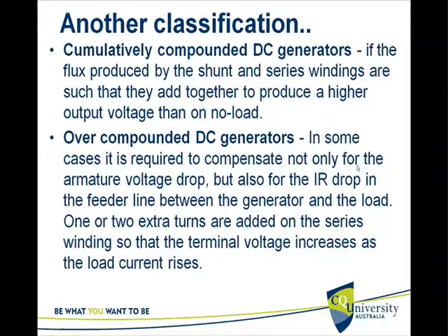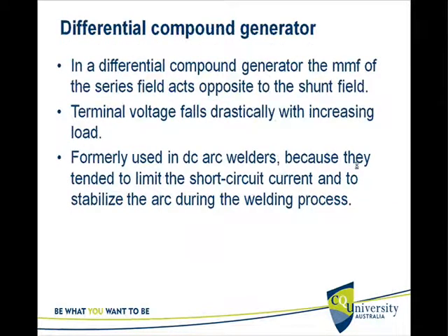What we do is add a couple of additional turns in the series field winding so that the terminal voltage increases as the load current rises. That is over compounded. And the other version is differential compound generators.